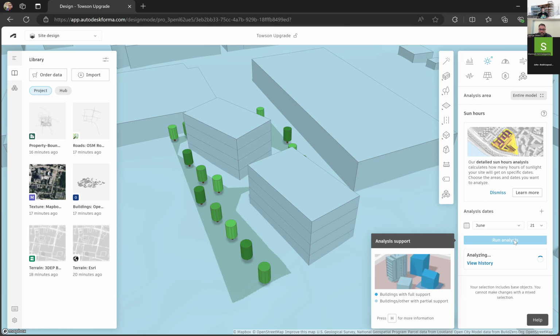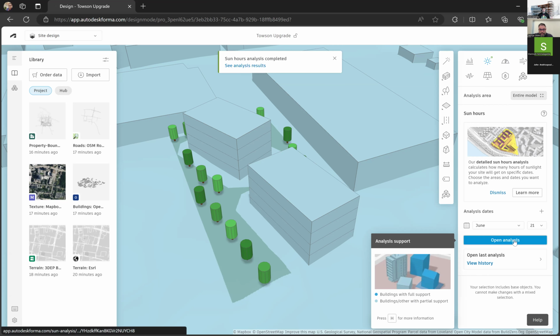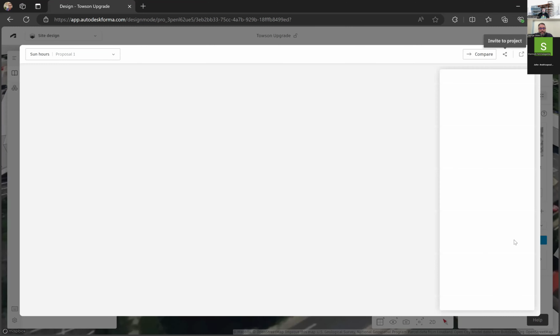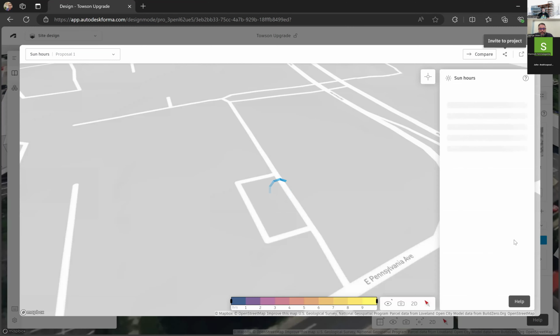One thing I like to add is, when you first select the model, it'll download all these buildings in the area. So if you selected a couple blocks, you can choose and pick which buildings you want to put into your proposal. You don't have to import all the buildings. You can manually select or do a window selection, say, okay, add these buildings to proposal one from the existing. That's a good base.